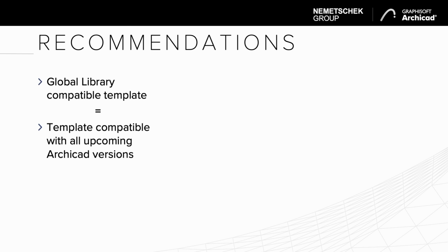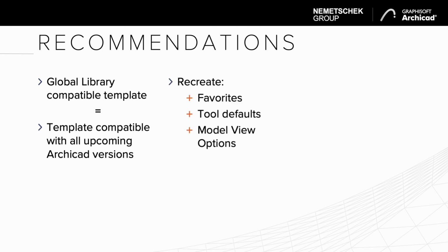We understand that recreating part of your template can be time-consuming at first, but once your template is Global Library compatible, it is also compatible with all the upcoming Archicad versions in the future. Remember to recreate your favorites and reset your tool defaults and model view option settings, since these were restructured with the technology change between the monolith and the Global Library.